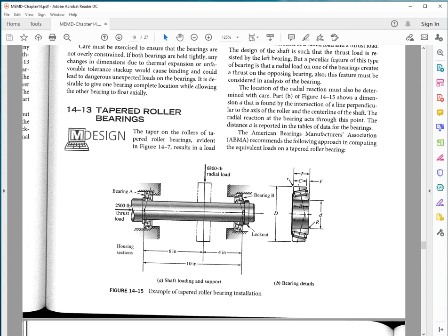If I mirror both bearings, then these intersection lines or the normals will intersect the axis of rotation towards the portion in between the bearings. So there's a reduction of the apparent length or distance between bearings by doing so.